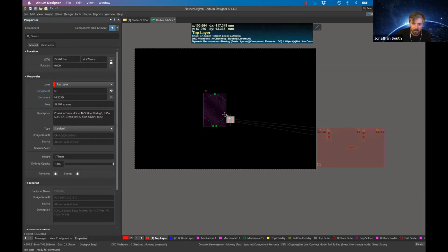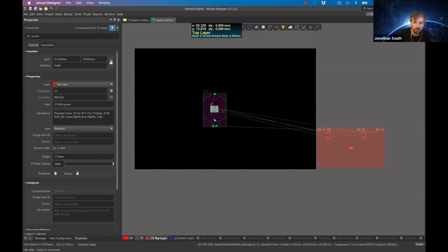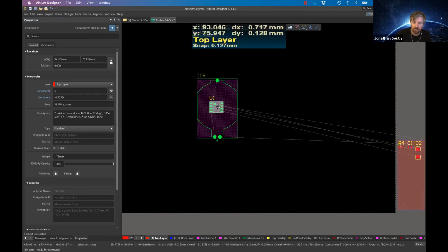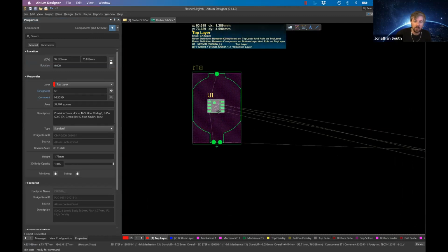I'm going to take my U1 next, which is my surface mount, and note that this is a surface mount any 555 timer. So surface mount, you can get away with things that happen on one side of the board completely separately to what happens on the other side of the board. If this was a through hole 555 timer, you got to think about what's on the other side of that board. So there could be a collision.